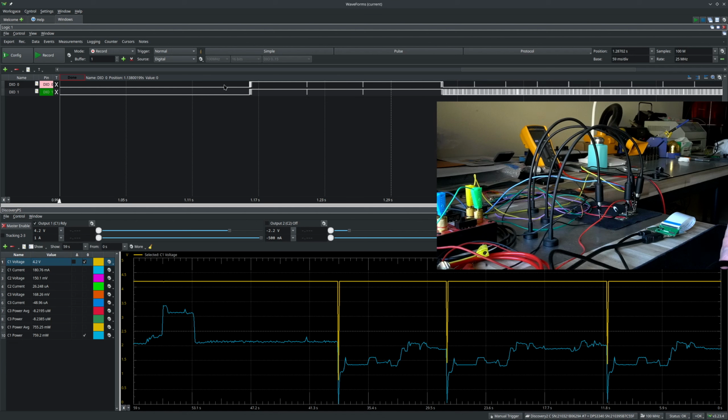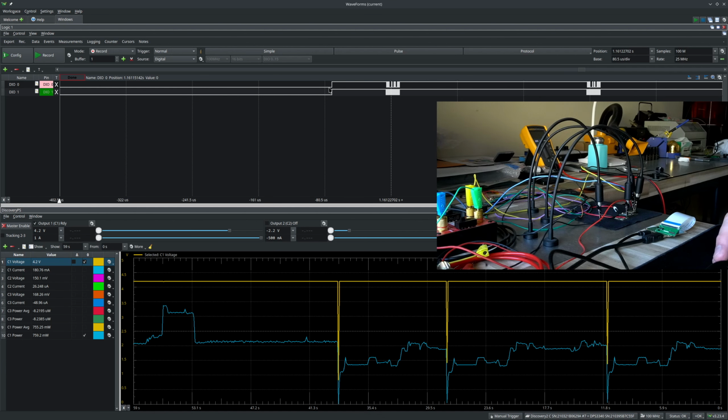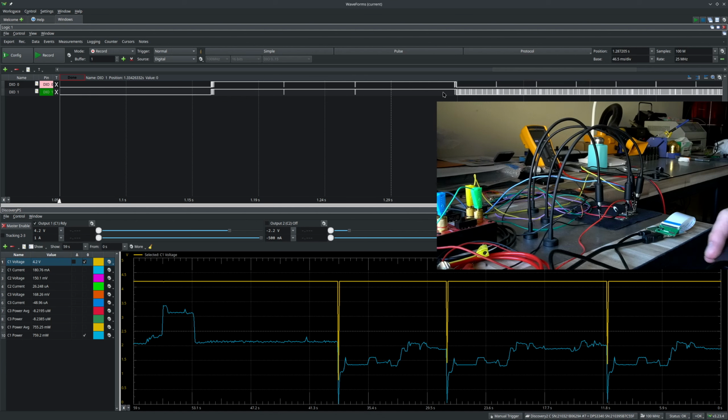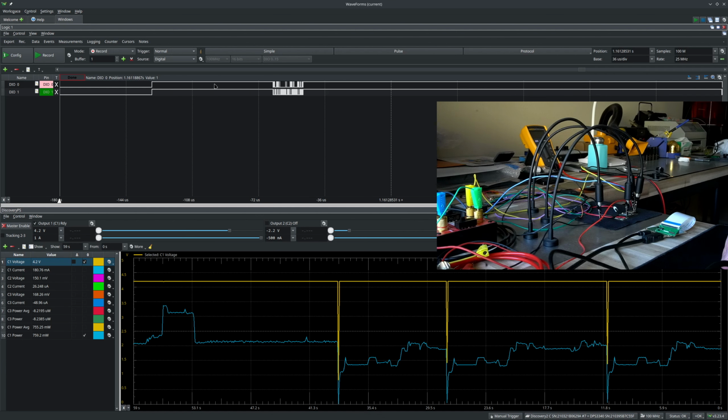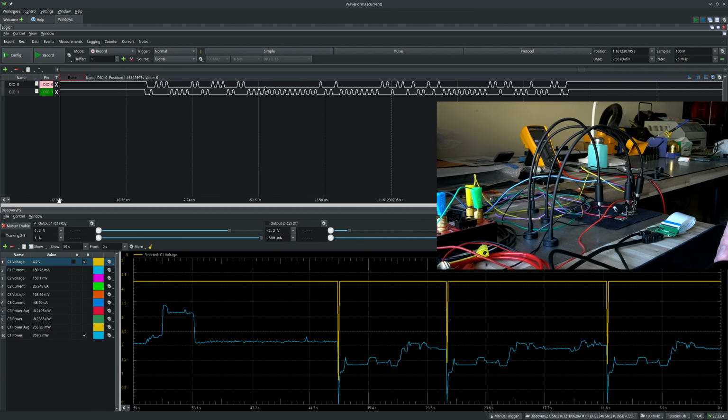So you can see when both lanes go into LP11 state here, and then before data transmission happens there, which of course is kind of all messed up and unusable because this is just a normal logic analyzer not set up for any differential stuff. Before that, you can see low power data transmission here.